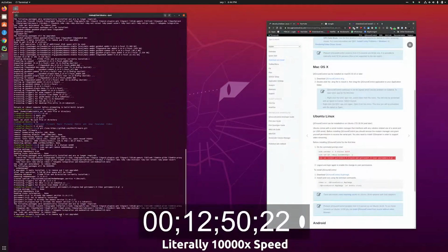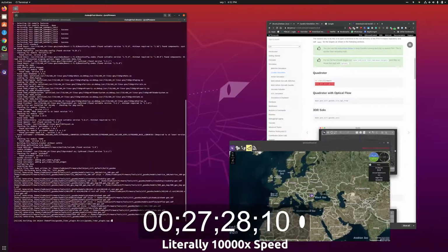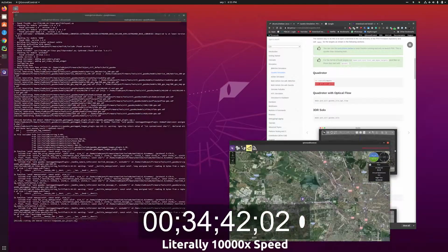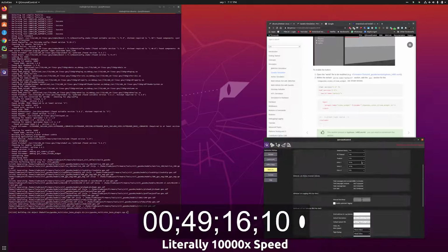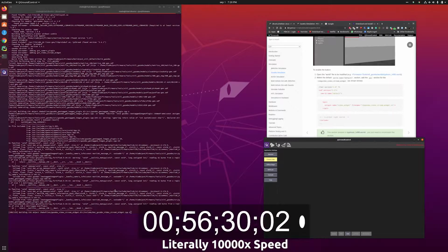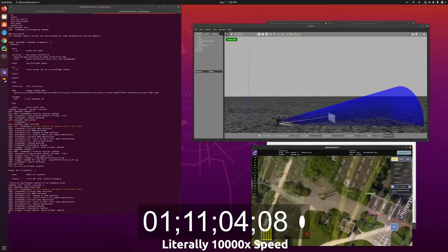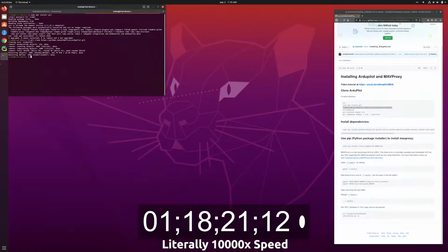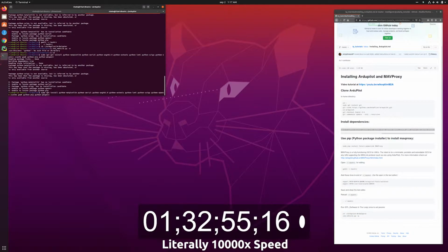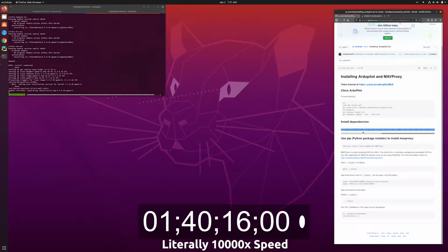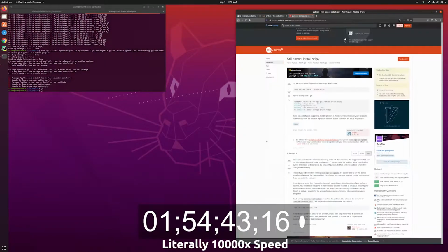First, I installed an application called Q Ground Control. I then went ahead and installed all of the dependencies required for Gazebo to function in parallel. After that was done, it was a matter of linking the two together so that the inputs made in the control software were reflected in the simulation. However, Q ground control was using a firmware called PX4, which is slightly more user-friendly.